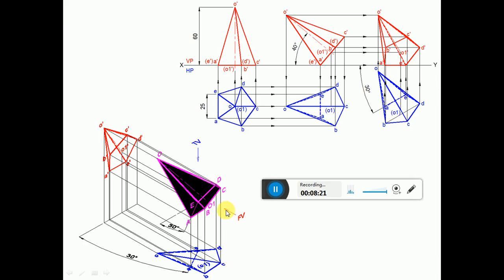You can see from the 3D also here, since the base is near to the observer, it is visible. So here all the exterior edges of the boundary, O dash A, AB, BC, CD and DE are the visible edges. So this condition and this condition will remain the same, and this is how the object will look when it is in the three-dimensional final position.